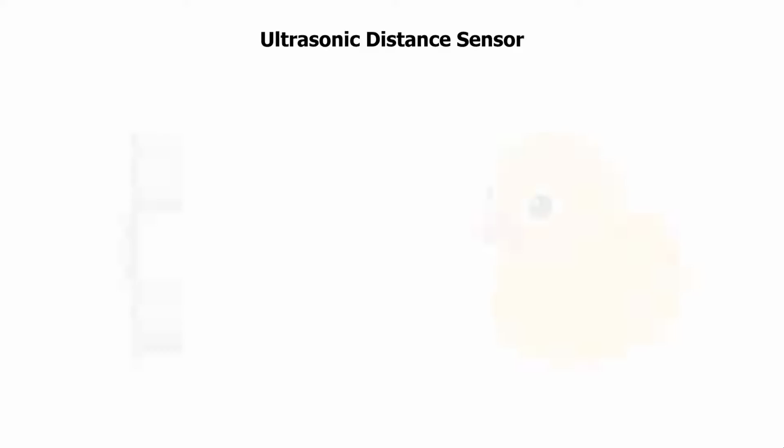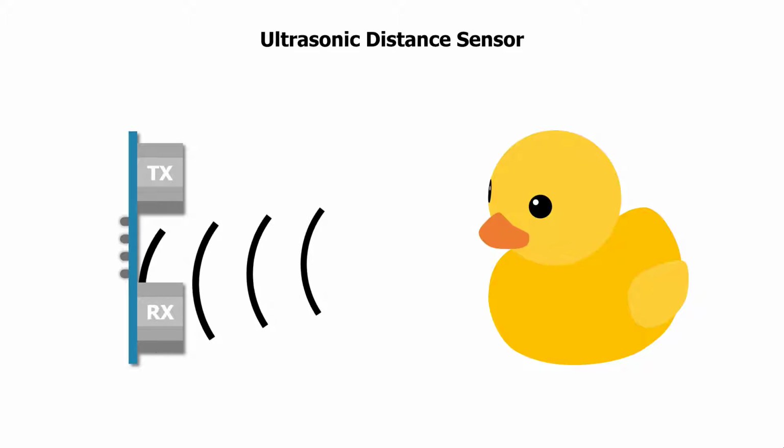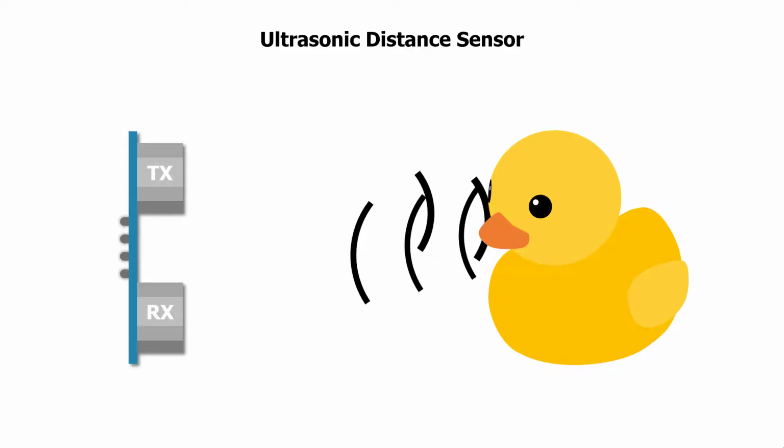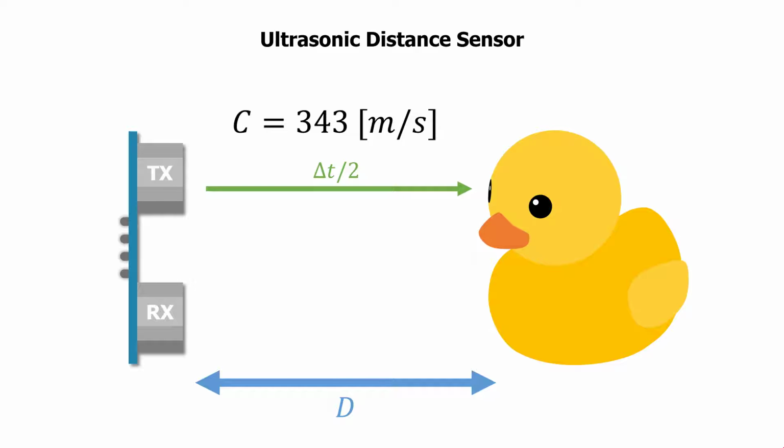When triggered, the speaker sends a burst of sound waves that travel through the air, hit any objects in the way, and reflect back to the sensor, where they will be picked up by the microphone. The speed of sound is approximately constant through air. Therefore, the distance of an object can be calculated by measuring the time it takes between transmitting the sound signal, having it reflect off the object, and receiving it at the microphone. The longer the delay, the farther the object.